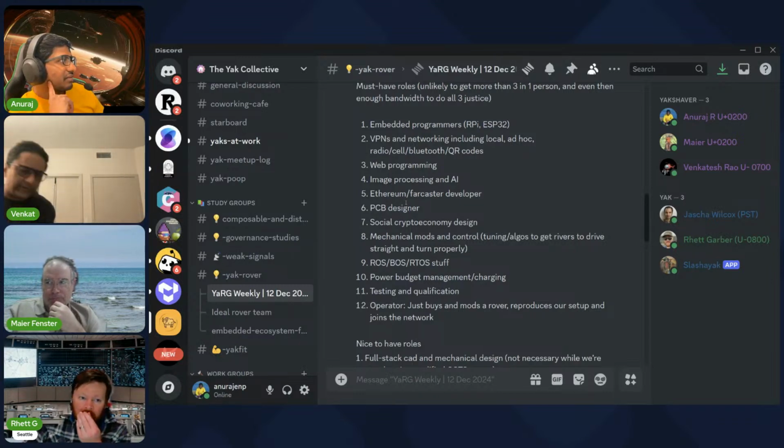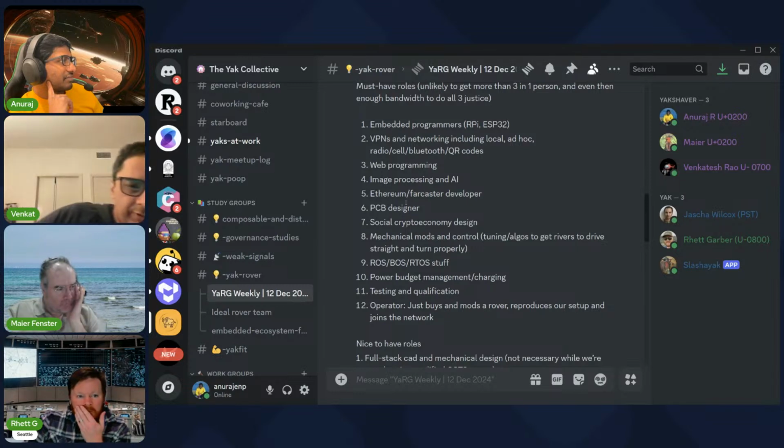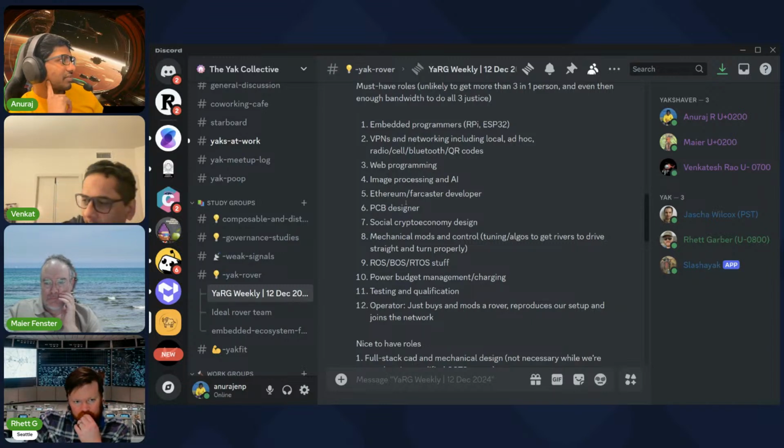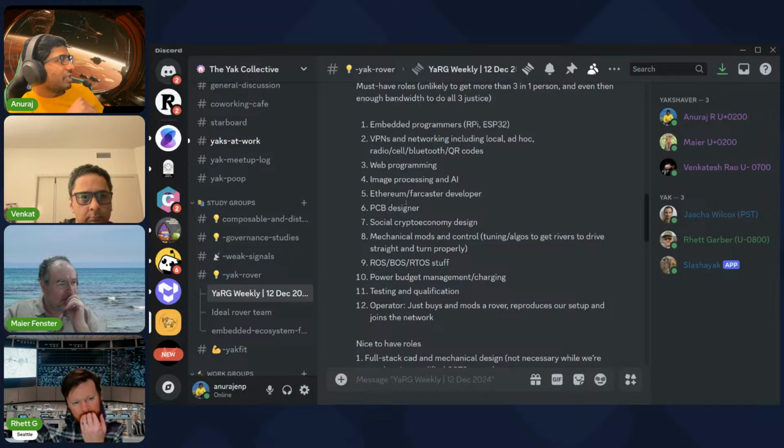Actually, can we discuss this 3.3 versus 5 more generally? Like the ESP is 3.3, but is that a general industry trend? Why is everything moving to 3.3, what's the whole logic? So you save power, right? Is that the only reason? Well, basically, initially TTL was just 5 volts, and then when 3.3 CMOS came out, everybody started moving to lower voltages. These days, you can also run many of these microcontrollers at 1.8, because if you have battery-powered stuff, the lower the voltage you use, the less power you use.